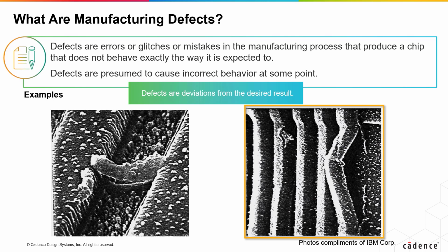If the buckled trace is not touching the other trace, there may not be a functional error, but do you want to ship it? Will later mechanical vibration cause it to either short to its neighbor, or might it break off and create an open? There is damage in a line across a number of traces, so there is more going on here than that simplistic analysis would suggest.